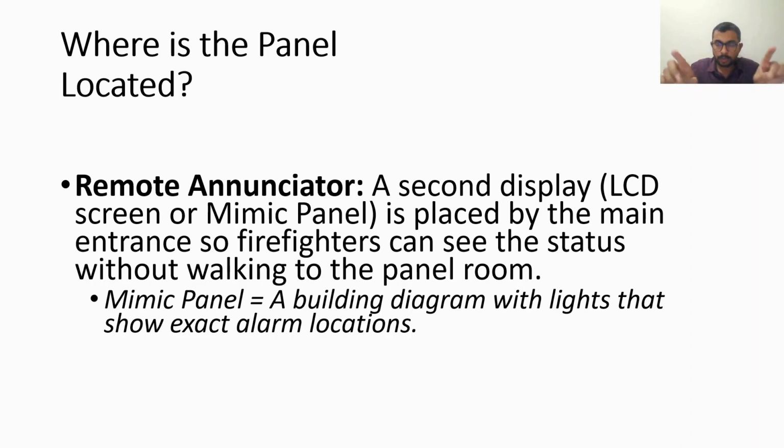It's like the building layout with so many LEDs in it. So each LED will be representing a zone. If that particular room is assigned as a zone in the panel program, and if the fire is activated over there, then that particular zone in the layout will be glowing red.